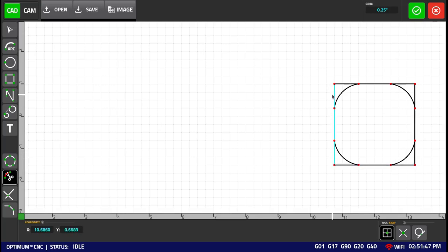You can see that the whole line gets highlighted, so if we were to click on it, it would essentially delete the whole line. So we don't want that. Instead, what we want to do is we want to find an intersection of this arc and this line right here. So now, after we found this intersection for all 4 lines, we essentially have a number of smaller segments that we can then delete.